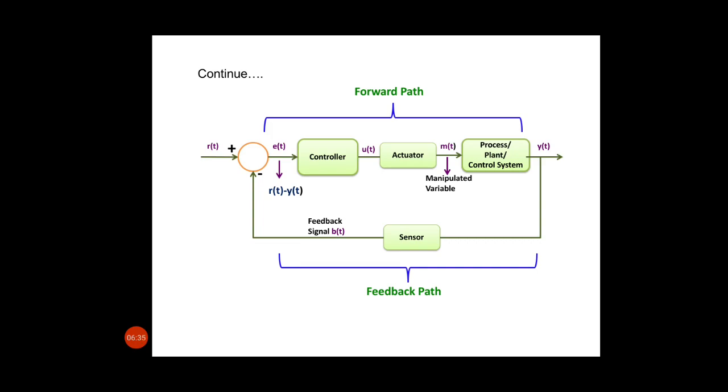On the other hand, if the system response is at a matter of seconds and the sensor also has a corresponding response time in the order of seconds, then I may need to incorporate the effect of sensor dynamics. So typically sensor dynamics may come into the picture when we consider the feedback path, and by analogy an additional component called the actuator comes into the forward path.